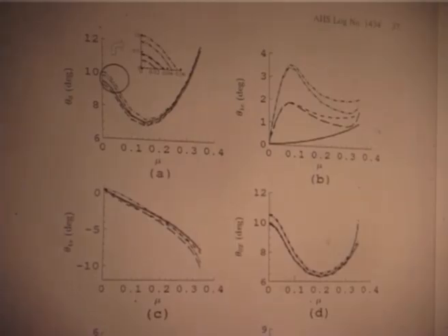If you reduce the drag of the fuselage, but how do you reduce it? That is the problem. That is why that F which I showed you, the equivalent flat plate area for the helicopter, has to be brought down somehow, then the curve may tilt and you can go further. If it is there, you just cannot trim, the drag will shoot very high. That is one of the key things.